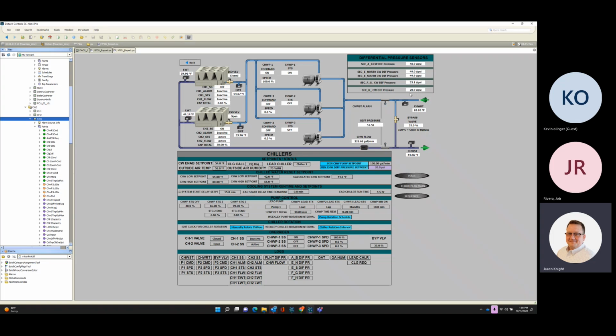If this were to continue to drop, let's say 15 pounds, then it'll kick pump 3 on, and pump 3 speed will stage from 0 to 100% to get back up to that minimum, whether it's H, F, or G. It's always going to be H, because H is the furthest away. It's the hardest building to pump to.